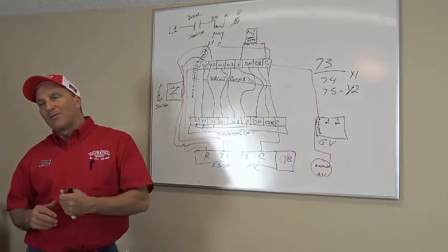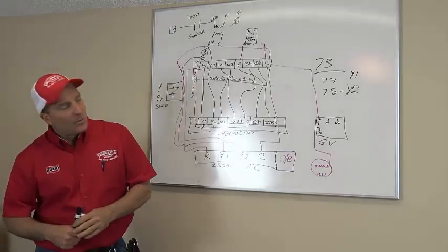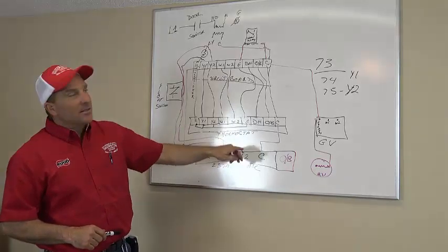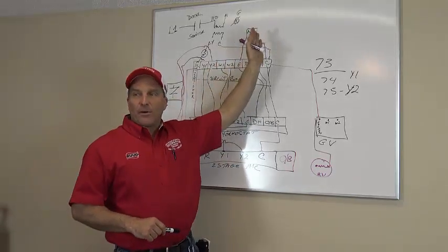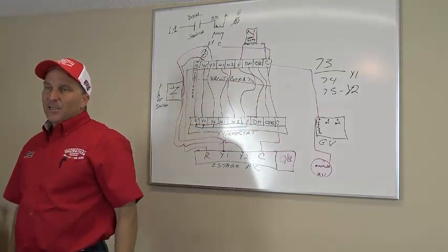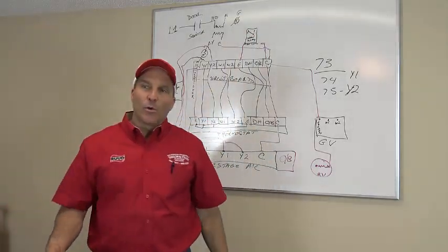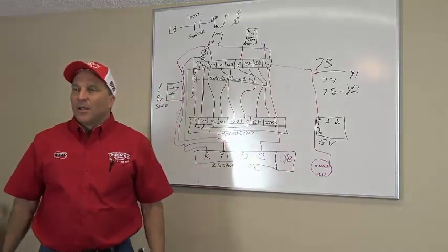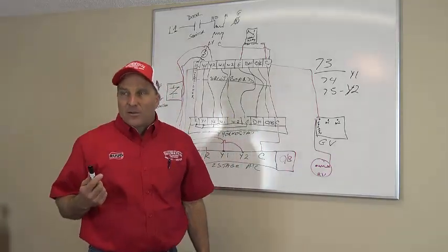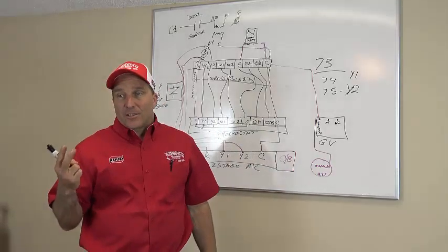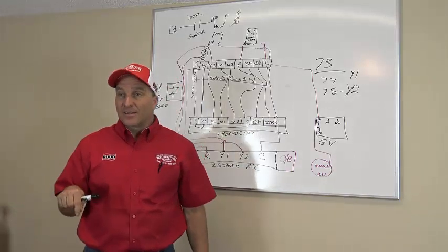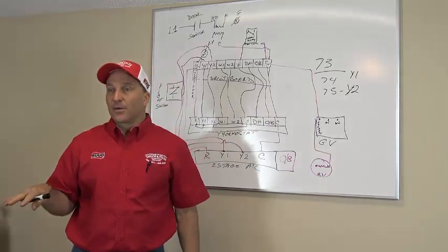We could actually have a blower relay in there that when energized, when Y2 got energized, it could take the fan off of low speed and then put it on high speed. Okay? So here's the way I would do it with the old Rheem systems. If I turn my air conditioning system on and I got a 2-stage air conditioner, listen how this works, okay? Because this is still in effect today when you go out there and see things, okay?